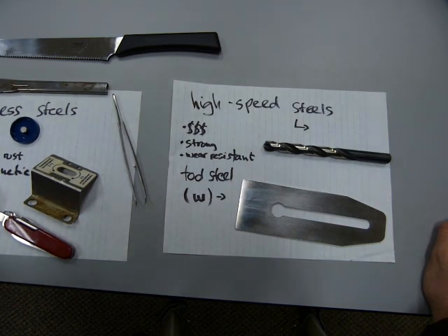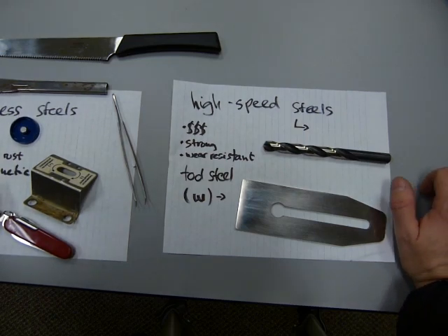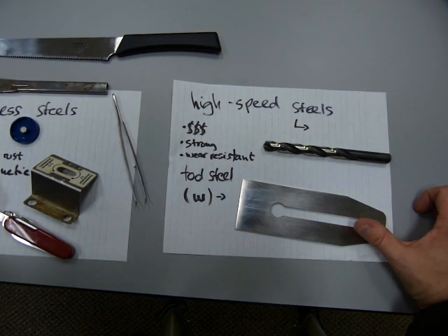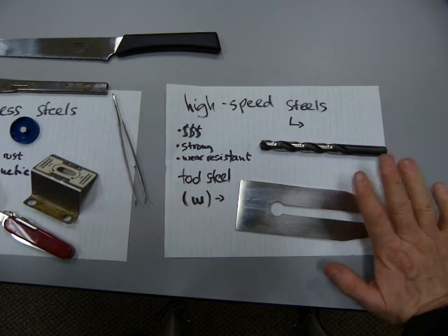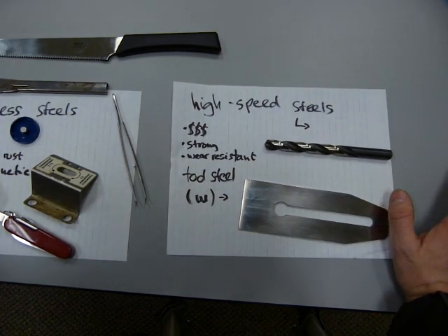They are also a lot stronger and a lot more resistant to wear. So high carbon drill bits will go dull. High speed drill bits will not go dull so easily, because these blades are extremely wear resistant. That also means that rehoning and resharpening these is going to be an effort.